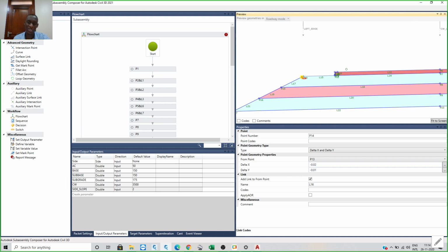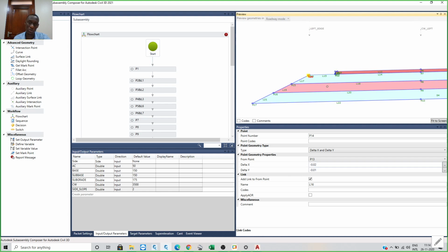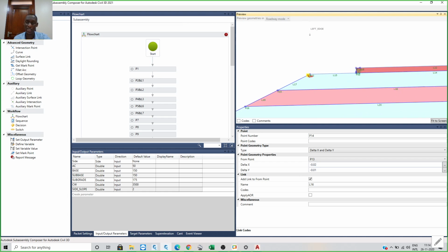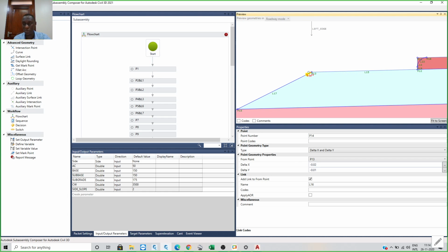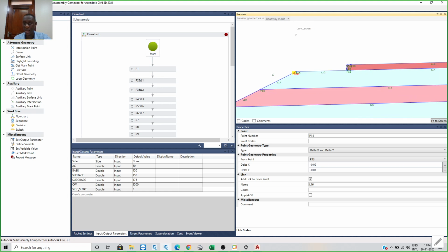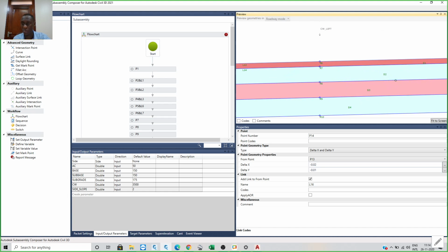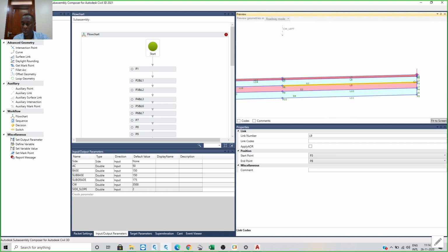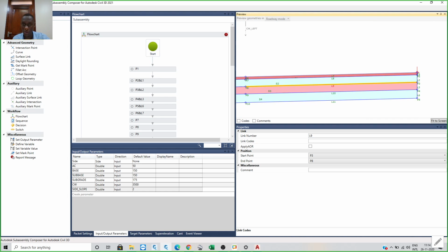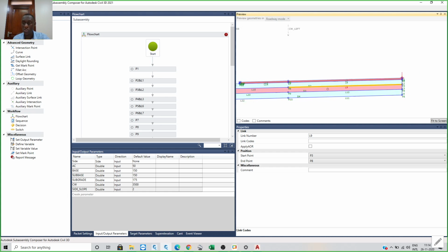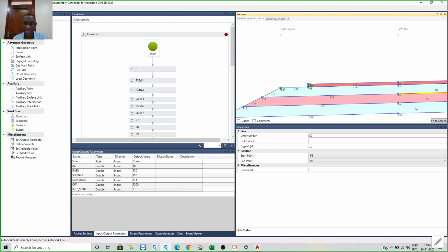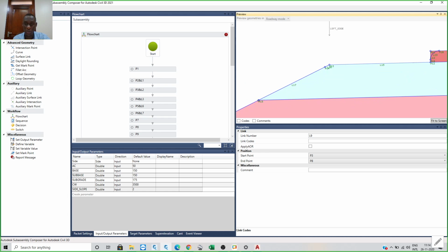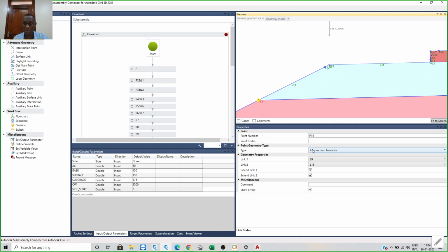Yes. So we use the intersection tool to intersect the link which is coming from this position. This one I made short, particularly for that reason, so that it can intersect this link which we already had from before. These links were joined by joining the points from the depth of the previous pavement layer. So now if I join this link and this other one, I came up with an intersection point here, which is P15. P15 is our intersection point.